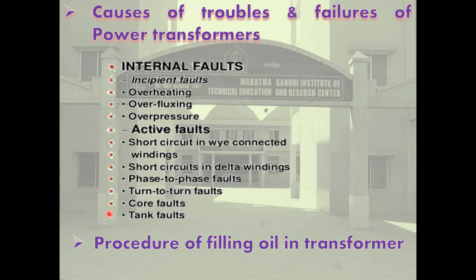The comparison between the centrifugal type and streamline type purifier. Streamline purifier can remove even fine carbon particles from oil because of the filter press. Centrifugal type of filter removes the moisture and gases more efficiently because oil is preheated and then spun at high speed. Streamline purifier requires special quality of filter plates.